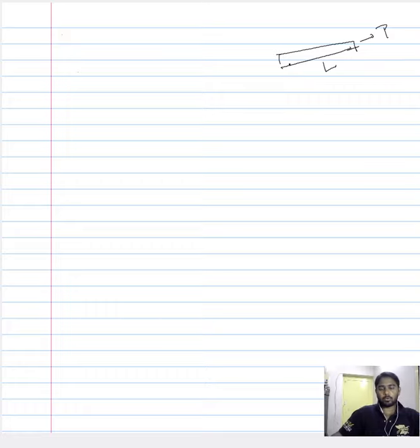For that, we wanted to quantify the mechanical condition in such a way that it was independent of the dimension of the specimen. So therefore we normalized the mechanical condition with respect to the area of cross section of the material, and thereby we ended up with a description for what we now call stress. So stress is nothing but the ratio of load that is acting upon a material and the per unit area of the cross section of the material.